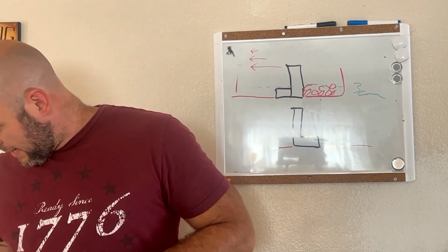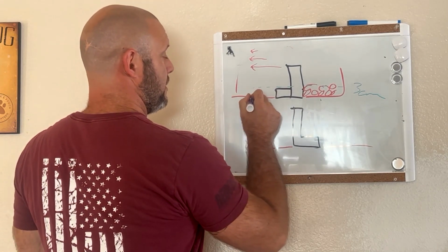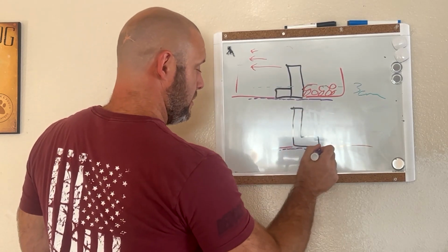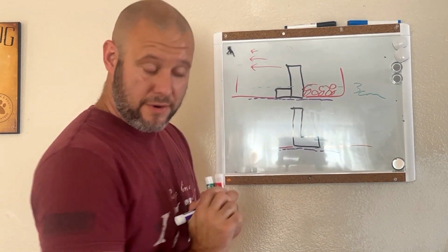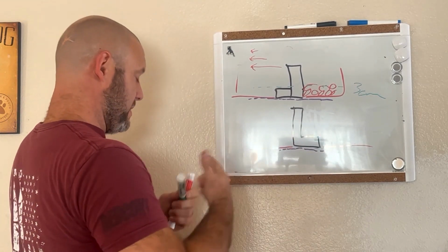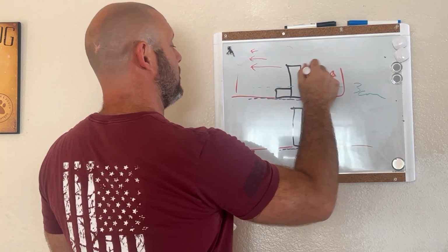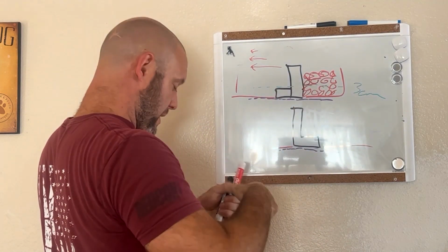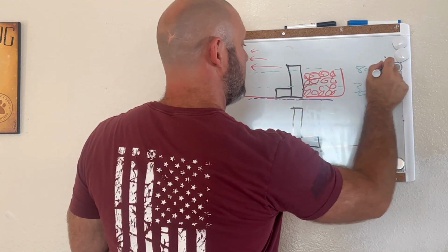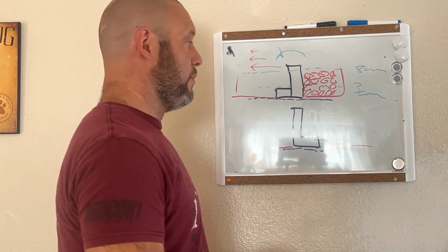Afterward, they came back and put the geomaterial simulation down at the bottom here to help increase the skin friction of the bottom of the retaining wall and prevent the sliding forces. When they did so, they were able to continue filling this until they had about 8 centimeters tall, and then they experienced the overturning failure that you would have seen.